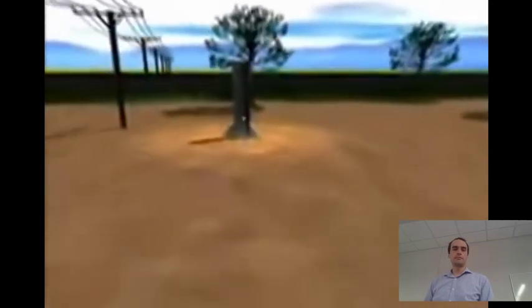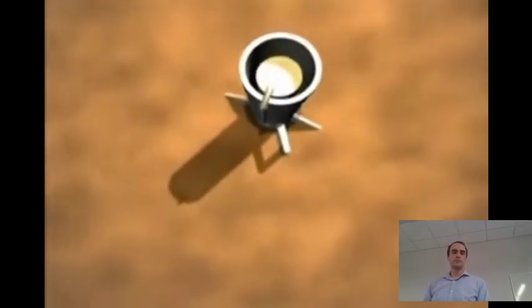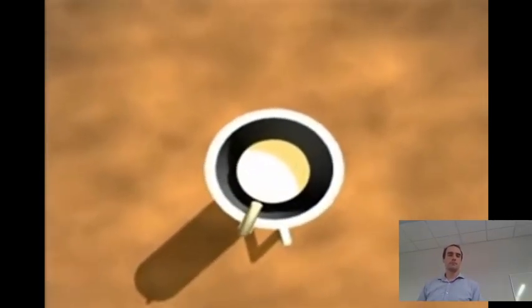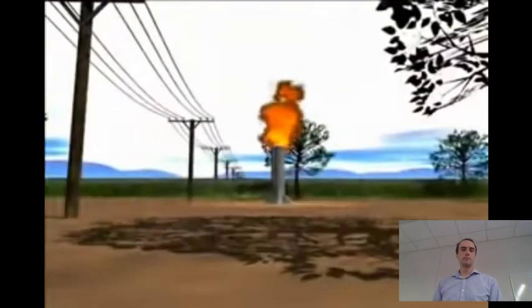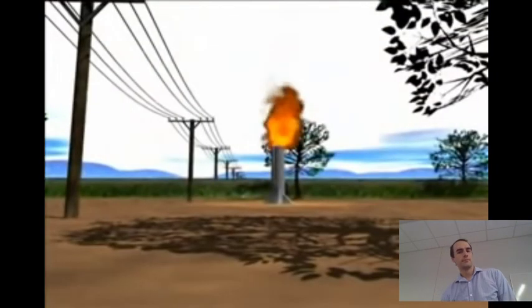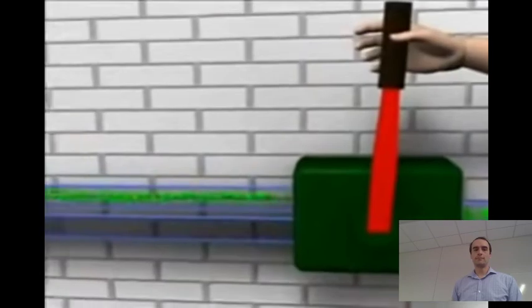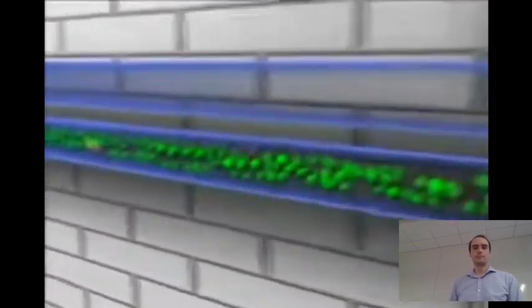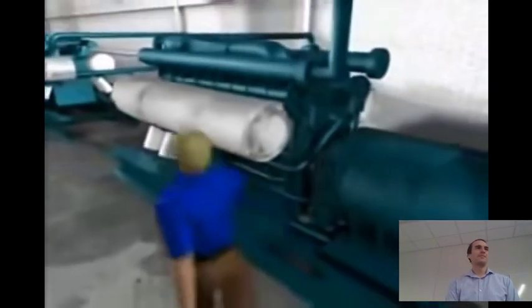In case of any overproduction of biogas, it is necessary to operate a gas flare, for unburned methane that escapes into the atmosphere is harmful for the climate. The biogas from this biogas plant enables two-block heating and generating power stations to run and be CO2 neutral. To annually process biogas from 15,000 tons of biomass, this plant must produce a total of 500 kilowatts of electricity.